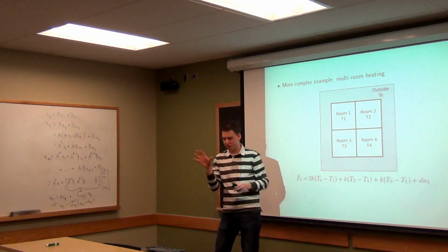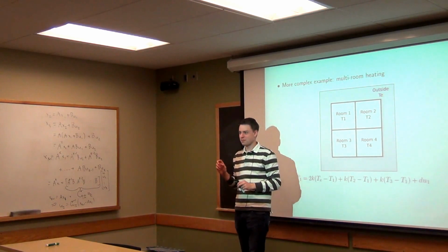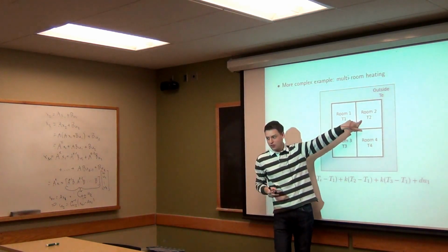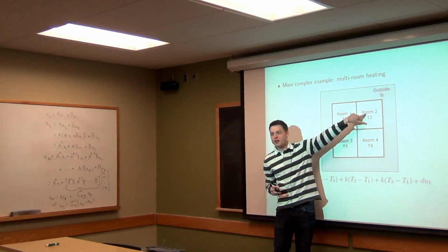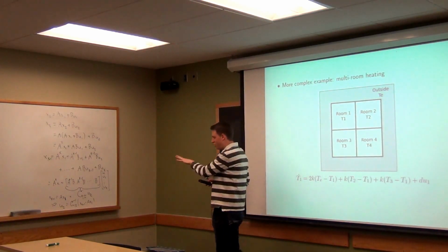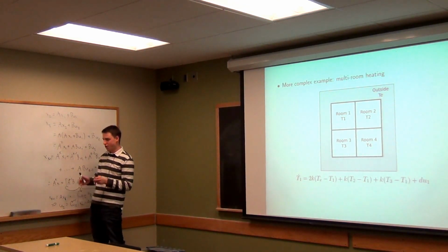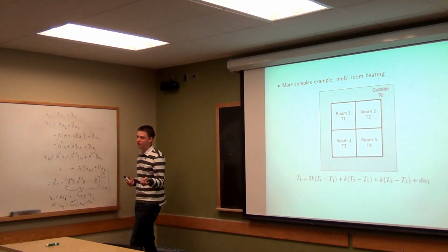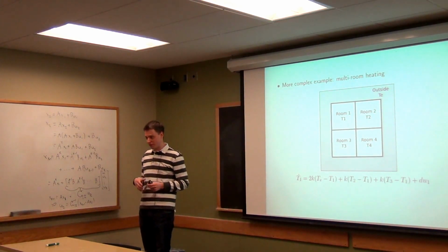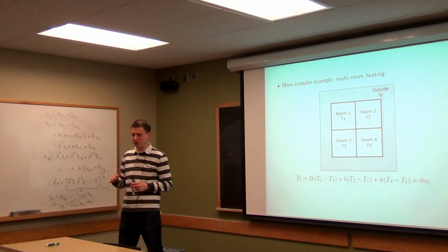Right? Because they're going to be exposed to the exact same conditions always. So that system is not controllable. On the other hand, if you have the things in these 2 rooms, you actually can do it, always. So the rank properties of this matrix are very dependent on the actual problem itself. And you can't say what you would expect or not expect, really. You have to just basically construct them and see what they are. And that will tell you whether it's controllable or not.